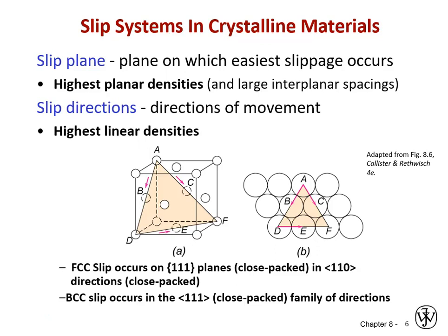But it doesn't have all that many of them, and so when you start to exceed the capacity of those particular close packed directions and planes to move, the stress required to activate the next easiest system is pretty high. So you'll have a fairly low yield stress for any given crystal, but you might start increasing the stress after yield fairly quickly. So you would expect maybe a fairly big gap between your ultimate tensile strength and your yield strength in that case.